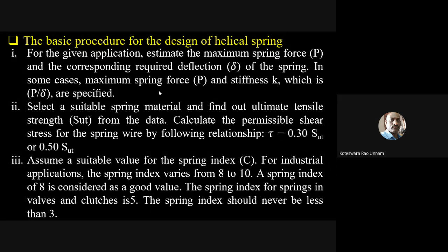In the same procedure here, the spring material is not mild steel. It is some steel material, some patented steel or cold drawn steel, which has undergone some kind of heat treatment also. That's why straight away I cannot take those values. But here the relationship for calculating the allowable shear stress is taken as 0.3 times SUT, so 0.3 into SUT is equal to your SYS.